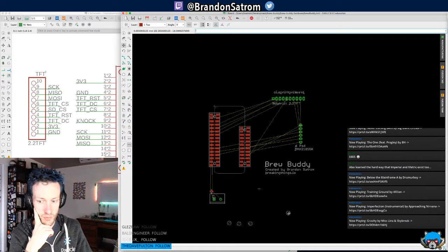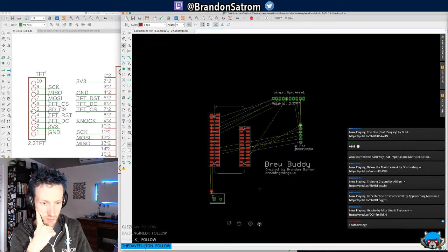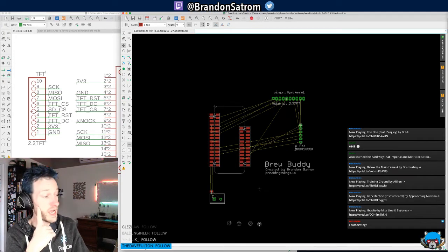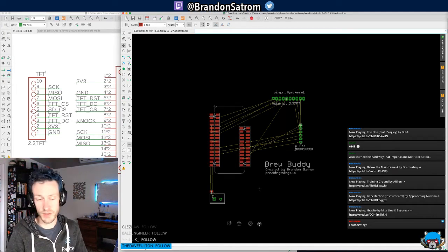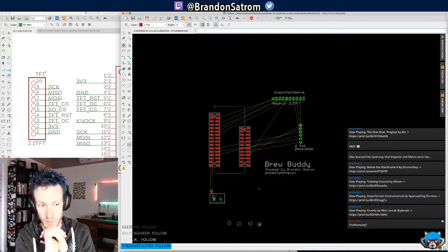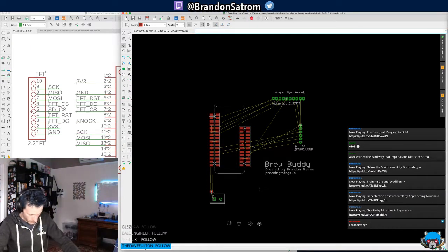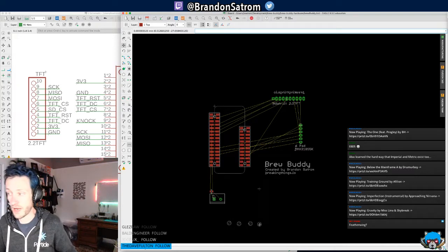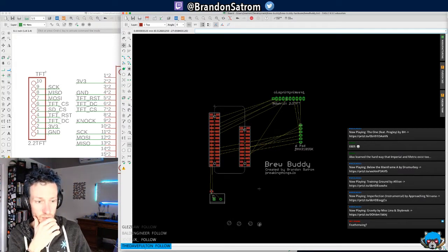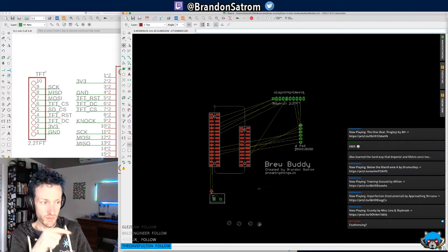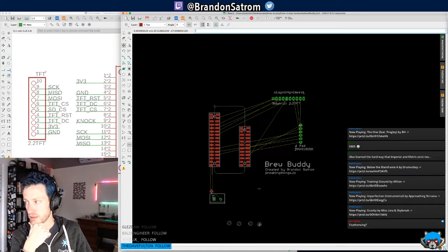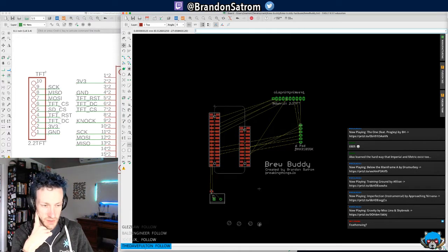So I had a 3D printed enclosure for this before, and I'll probably bring that back around. Featherwing. Yeah. So the Argon, all the new devices, the Particle Argon, Boron, and Xenon are all Featherwing. I'll use the Featherwing form factor. So they're pretty nice to consistently work with like that. This particular footprint that I'm using is an SMD, a surface mount footprint, so I'll have to keep that in mind if I'm going to route anything underneath, but frankly this is not going to be too complex, so I'm not too terribly worried about it.